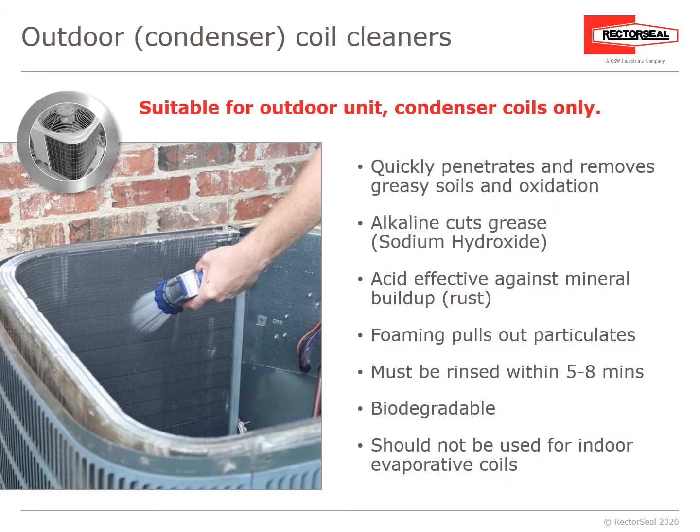In looking at the application for coil cleaners, let's first look at the outdoor condenser coils. You want to have a cleaner that's suitable for the outdoor unit, condenser coils only. A product that quickly penetrates and removes greasy soils and oxidation. Alkaline cuts the grease using sodium hydroxide. Acid is effective against mineral buildup and rust.